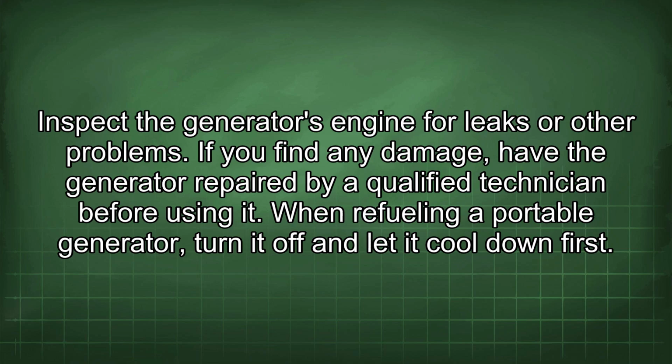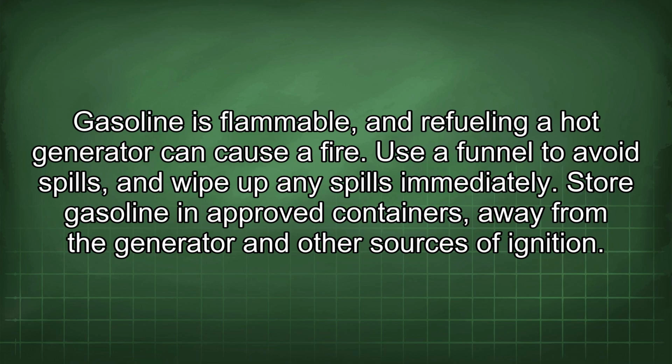When refueling a portable generator, turn it off and let it cool down first. Gasoline is flammable, and refueling a hot generator can cause a fire. Use a funnel to avoid spills and wipe up any spills immediately. Store gasoline in approved containers away from the generator and other sources of ignition.